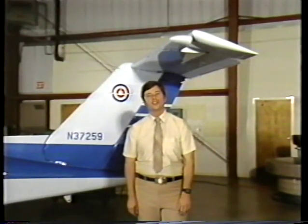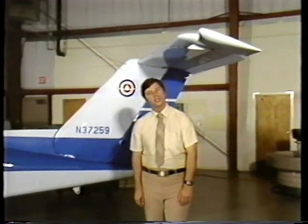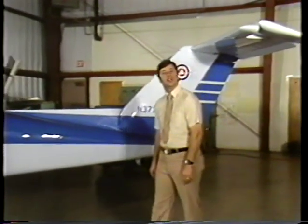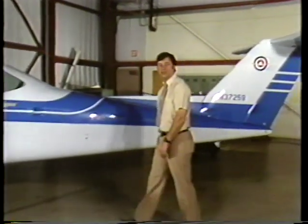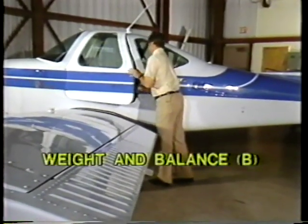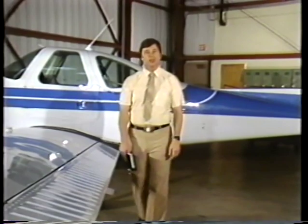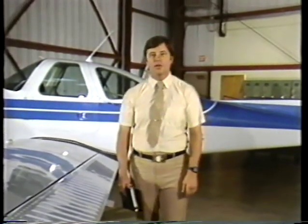Last time we discussed the theories of weight and balance and the computation method of solving weight and balance problems. Let's pick up where we left off and learn how to use tables and graphs to solve weight and balance problems. The next method used to compute the airplane's weight and balance is called the tabular method.